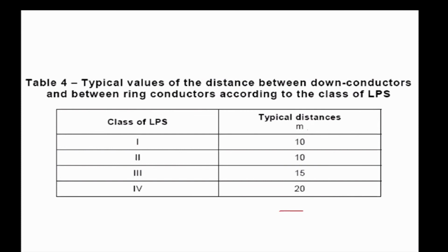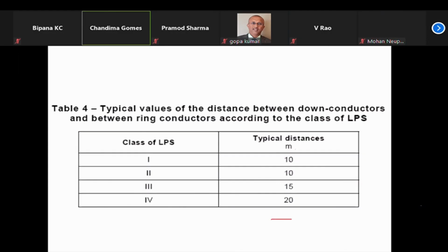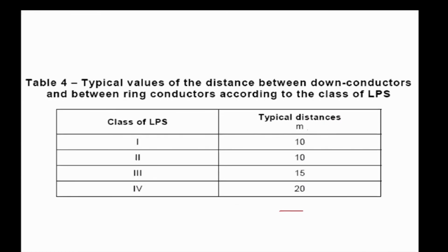Therefore, once you determine the number of down conductors, you place them as separated as possible, but avoid any inconvenient places and places where somebody might touch the wall or the termination. So don't stick to this separation itself, be a little practical.